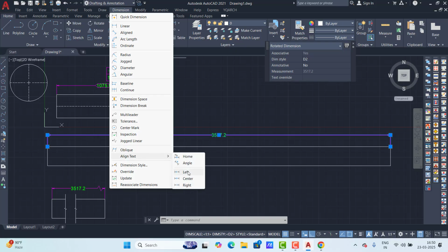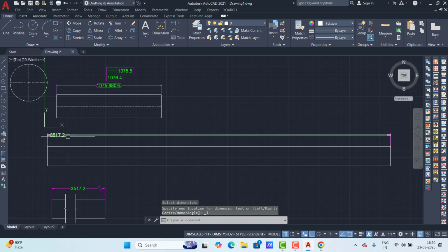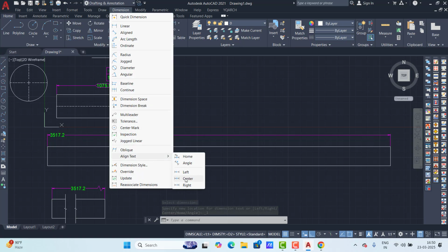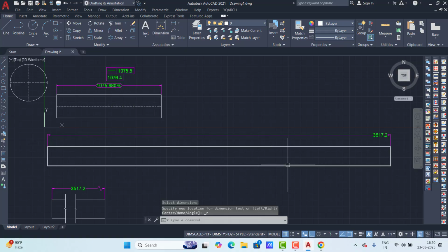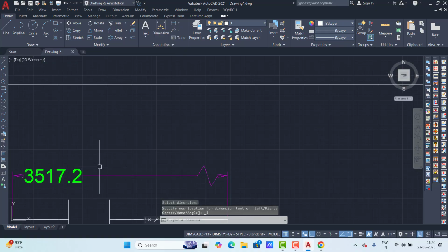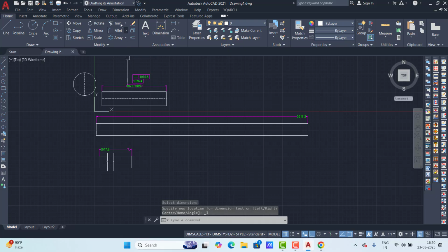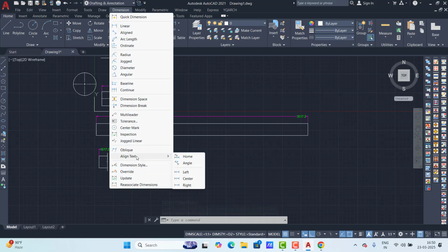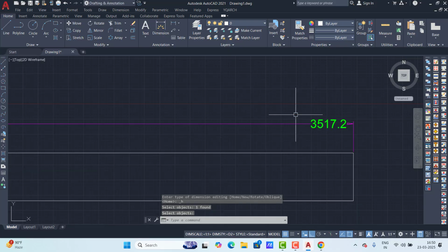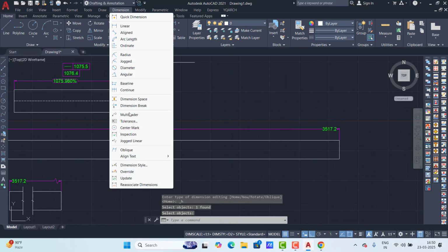So again double click this text to select it, go here to formatting and here oblique angle. Suppose this angle, this direction, suppose 30. So this is coming vertically, okay? 45, so it comes this way. 90, different. 10, so this way you have to manage. 0, minus 10. Okay? So minus 10 is something correct.